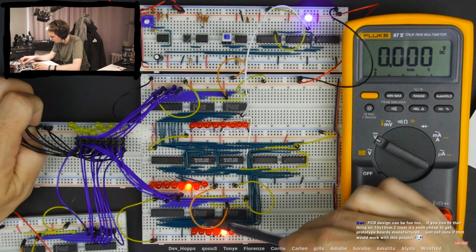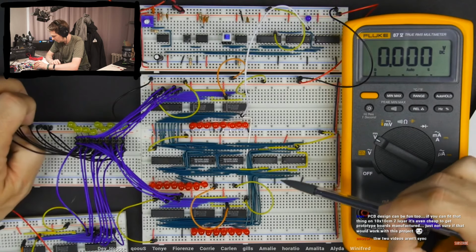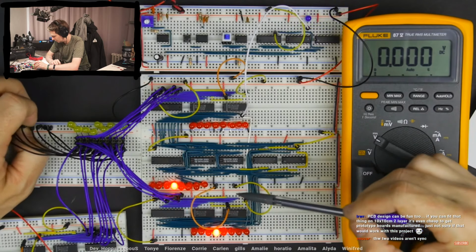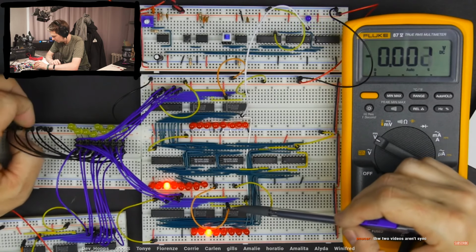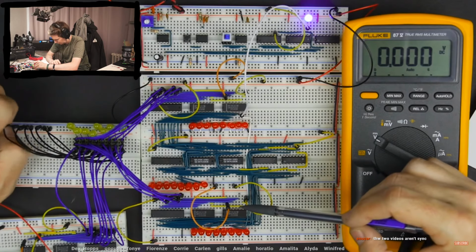Now it could be here in the connection from these bits down here to the XOR gates, or it could be from the XOR gates to the adders. It actually probably doesn't matter. Well, we probably screwed up one of them, but we could probably swap it back on either of those, as long as we have it swapped the right way around. But let's keep testing, see if we have anything else swapped while we're here. Okay, so the fifth bit looks okay. The sixth bit looks okay. Seventh bit looks okay, and the eighth bit looks okay. So it looks like we just swapped these two.